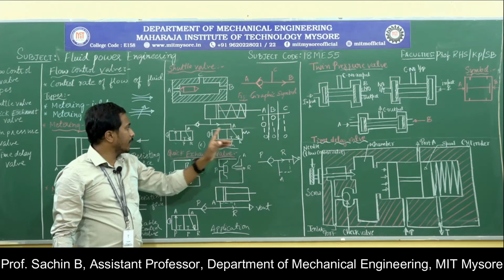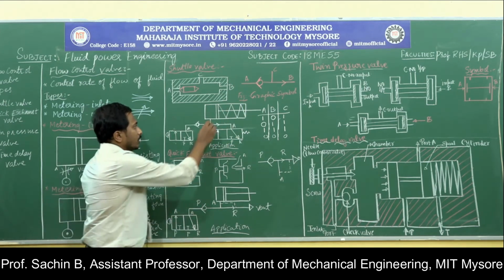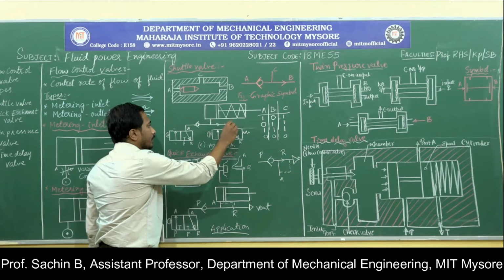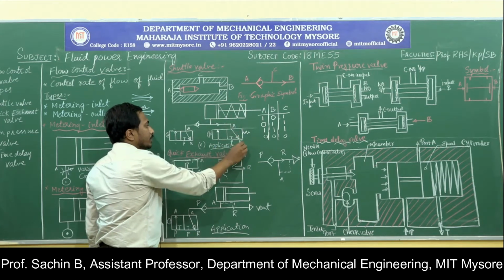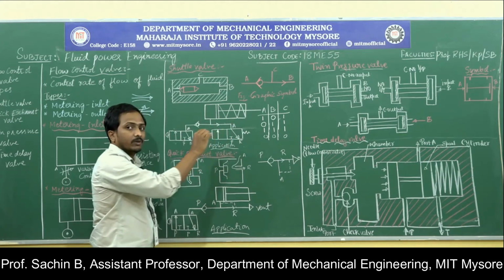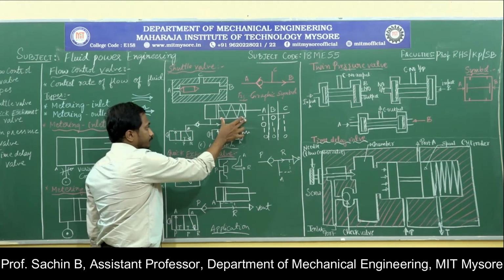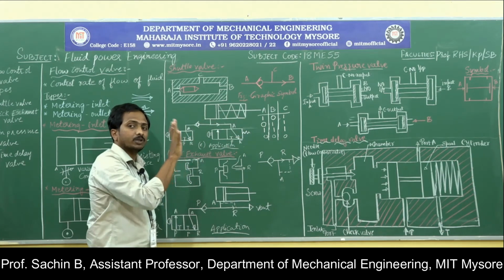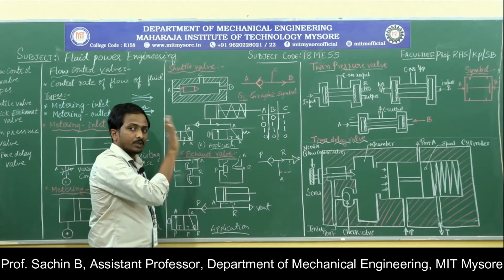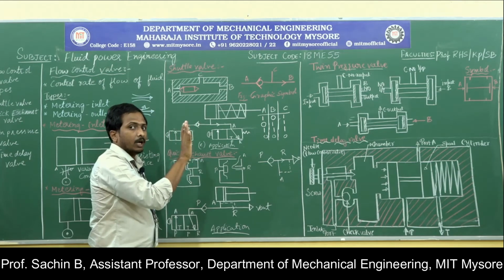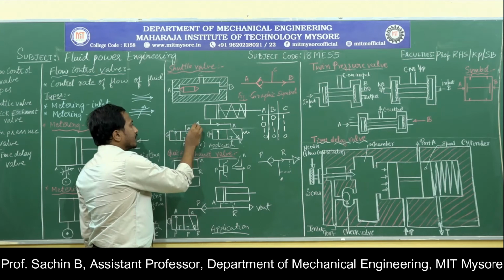And while retracting back, you can clearly observe this flow will get retracted. This flow will be returned to the reservoir with the help of port A itself, because of the compression force that is already present in the piston rod side. And also one more thing, some of them will get confused.